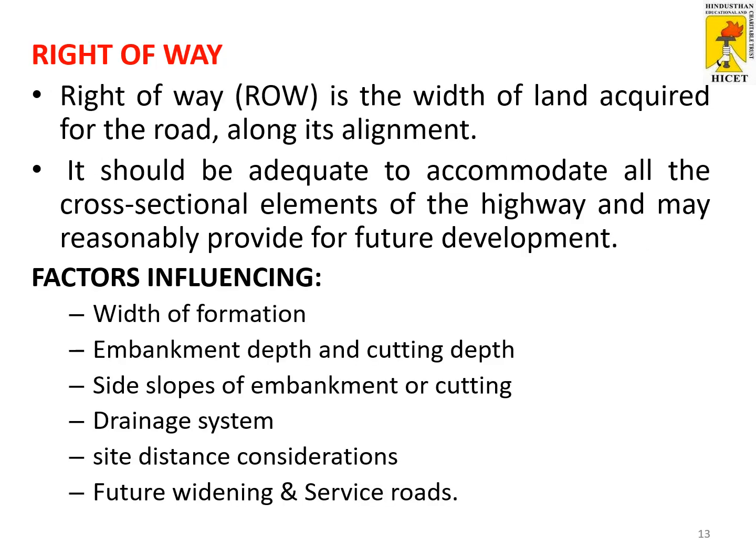Right of way. Right of way is the width of land acquired from the people to construct the road along its alignment. The alignment means the center line of the road. The right of way should be adequate to accommodate all the cross-sectional elements that we saw earlier and may reasonably provide for future development. So in order to extend the road in the future, we have to acquire land with respect to future development. Before acquiring the land, we have to consider some factors.